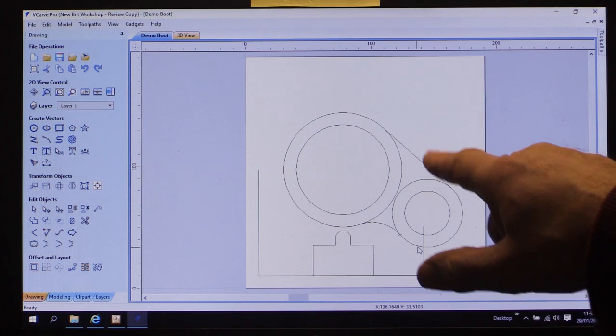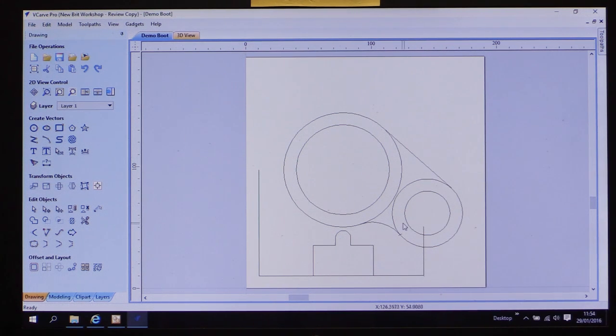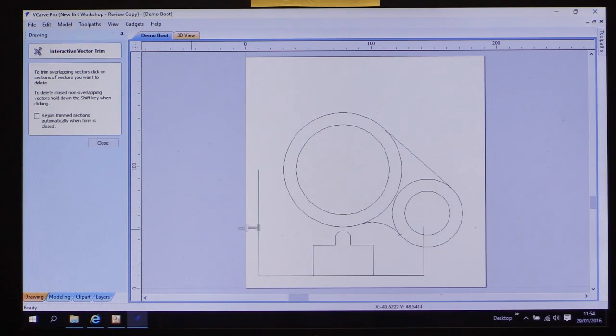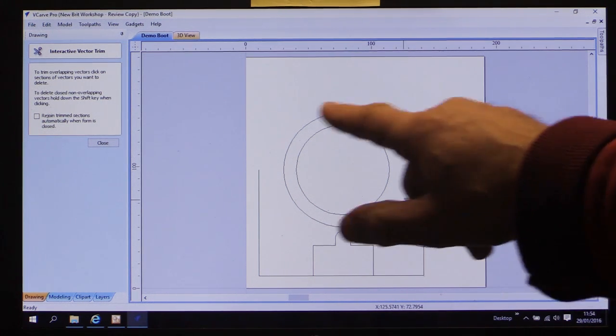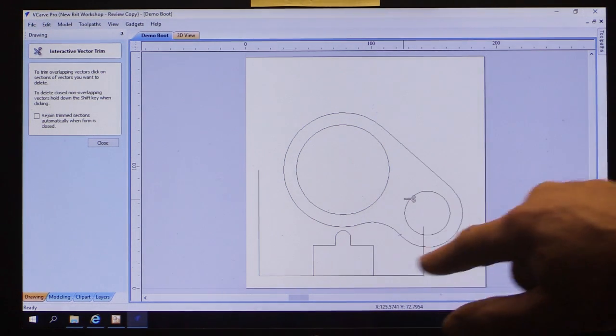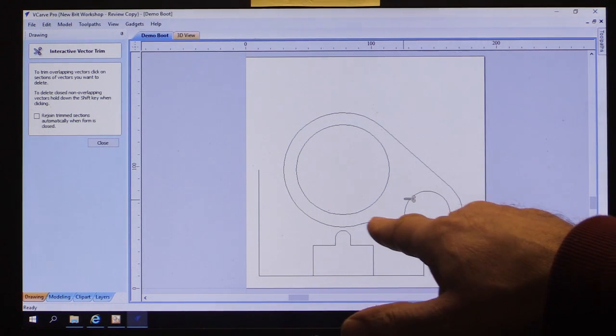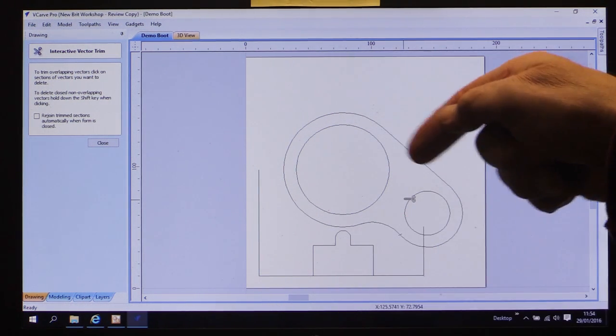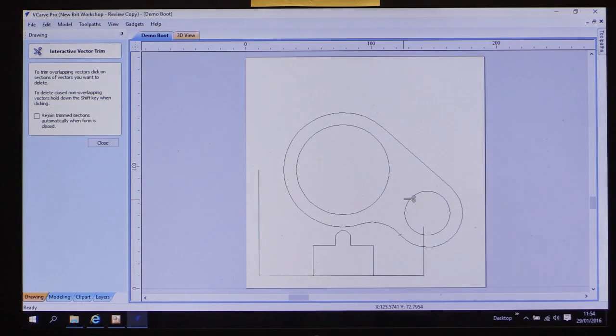And I think now you can see that if I now take my scissors command again, I should be able to trim this, and I should be able to trim that there. And so now we've got what is actually quite a good shape for the place where the bristles are going to go. If you want to have a rounded shape like this, just here, you can do the same again.